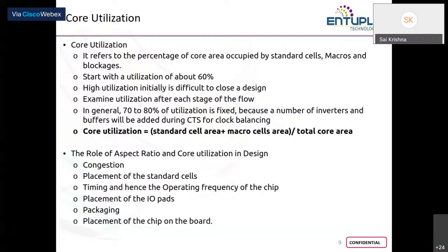Basically, as we have discussed yesterday, with respect to your timing, for any given path, if your slack is negative, that means your data is being lost and your functionality could collapse. Now, in order to make this timing better, you can add a series of inverters or buffers to boost up your signal.